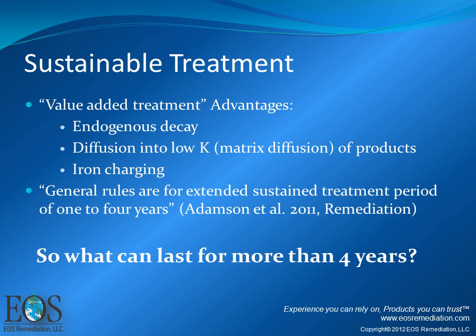The basic concept of this value-added treatment that Adamson et al. goes into, that's who the graph previously was from, talks about endogenous decay. With enhanced bioremediation, you produce a large amount of biomass, and that biomass stays in the subsurface and can kind of be recycled or reused to produce new biomass, which prolongs the life of the treatment.